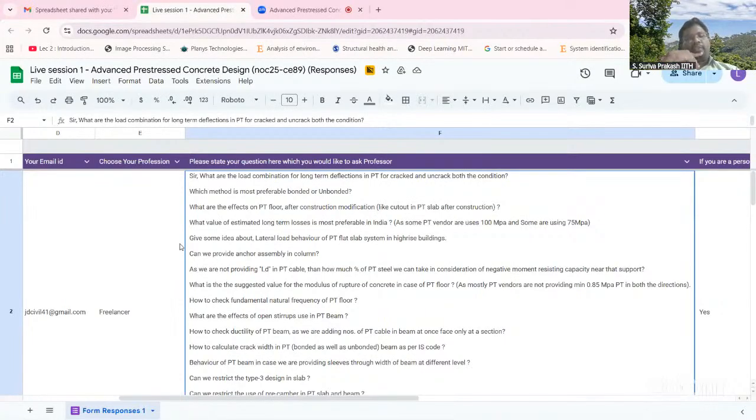The second thing is, if the beam is going to be part of the moment resisting frame that is helping in transferring the lateral load, then also we cannot have open stirrups. If it is just part of a gravity load system, then it's okay, right? Because in regular shear, it's a 45-degree crack, so vertical links by themselves are sufficient to arrest that shear crack. But torsion is also shear in a three-dimensional form, and that will induce a spiral crack. That crack will happen on all four sides. To arrest that, we cannot have open U stirrups. You need to have a closed stirrup, right?